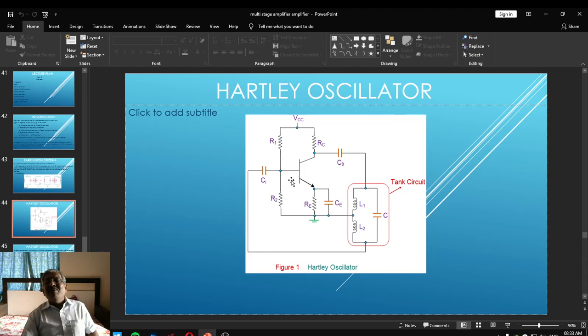As the transistor is NPN, the transistor is again forward biased due to the positive signal provided to the base, and again the transistor will be turned on and start conducting current. This current will again pass through the tank circuit. Meanwhile, the capacitor again discharges and this reverse current also flows to the inductance combination of L1 and L2 to start building up the magnetic flux, but in the opposite direction.